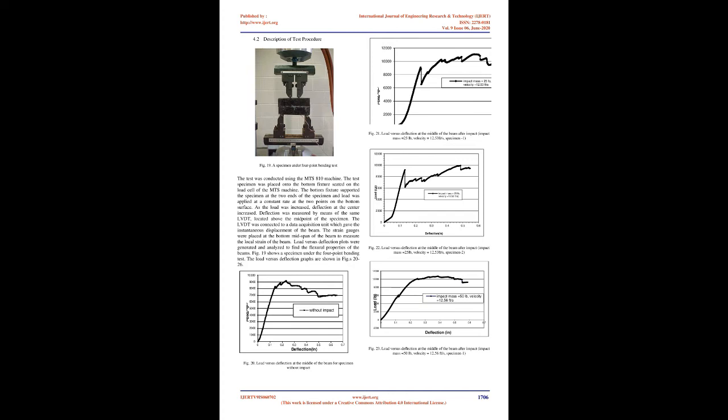When a critical load, peak load, is reached at the end of the initiation phase, the composite beam specimen may fail either by a tensile or a shear depending on the relative values of the tensile and interlaminar shear strength. From this point the fracture propagates either in a catastrophic brittle manner or in a progressive manner, continuing to absorb energy at smaller loads. In the impact tests, it was observed that the specimens failed by an indentation at the front skin, delamination of the skin, debonding of the skin from the core, and shear of the core. See Figs. 15 to 17.